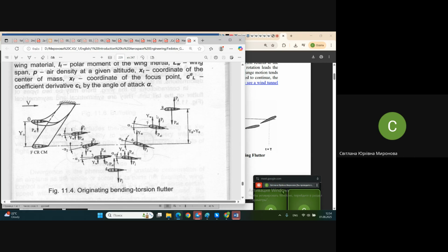But we still have the same arm to the control surface, but the control surface is not able to give proper force. Why is it not able to give proper force? Because the mode of downwash is abnormal, and so on. So control surfaces are working, but not sufficiently. There is a lack of control over the airplane in this case.